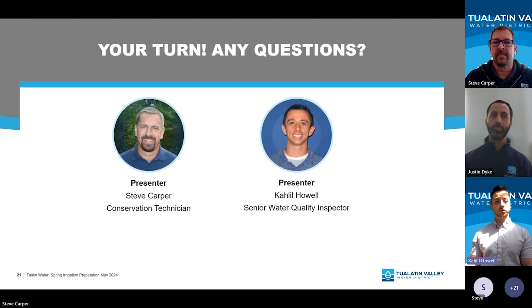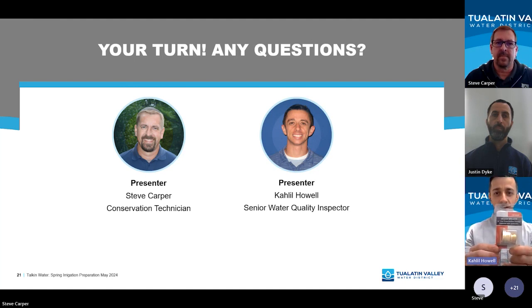Homes built afterwards would. However, if you looked at your hose bib and it did not have a hose bib vacuum breaker, there are retrofittable hose bib vacuum breakers that you could buy at a hardware store. We have some here.